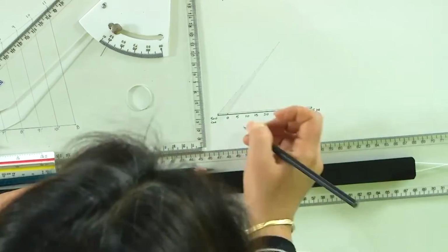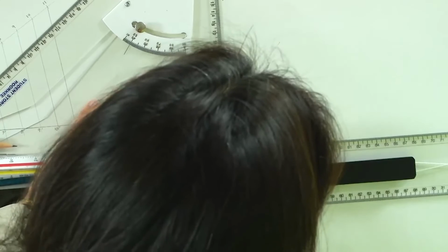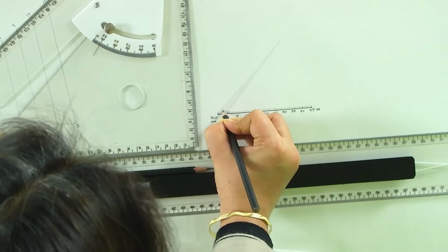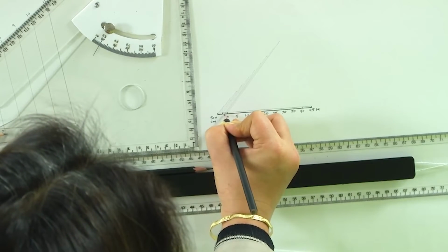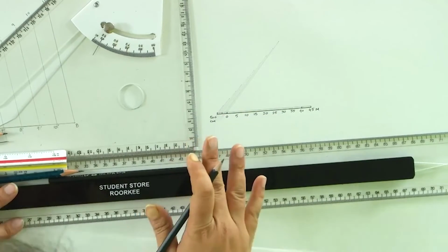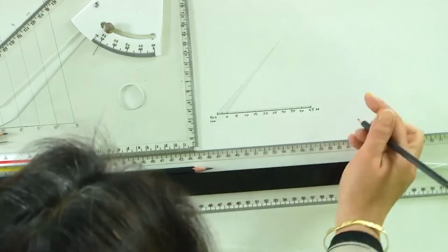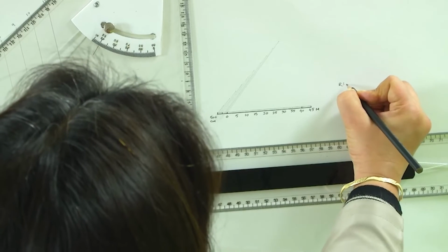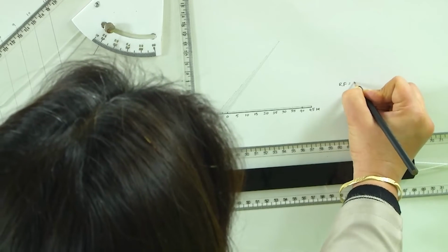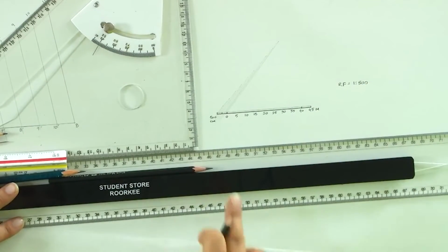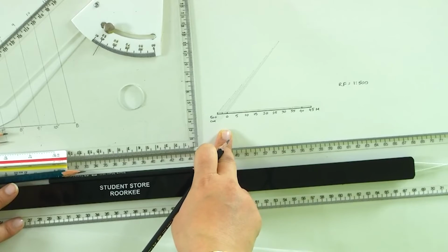This is a scale, and then for each division we could also mark these lines, or we could just mark the middle one, which is 250 centimeters, or we could also write the divisions in between depending upon the common unit, the dimension to be measured. This is a plain scale representing an RF of 1:500. That is what this particular plain scale represents.